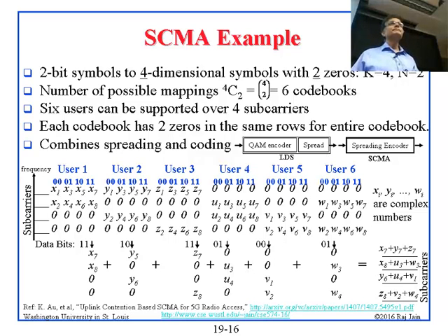How does the number of subcarriers factor into this? The more subcarriers you have, the sparser it becomes and the less collision possibility there is. The dense coding like here is really not that sparse. It is just 2 out of 4, and we are using all 6 possible codes. It is just more collision possibility, which means that if everybody started speaking, there will be more bit errors. Hopefully, not everybody will speak at the same time, and so there won't be a problem.